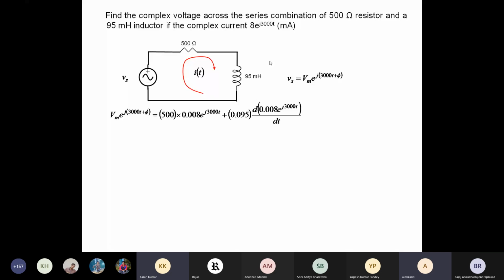So that type of thing. You see, your L is 95 millihenry, so it is 95 times 10 to the power minus 3. So it comes to 0.095 into d/dt of this current. Obviously it is in milliampere, so 8 will not be 8, it will be 0.008 e to the power j 3000 t. If you do this, you basically get this e to the power...